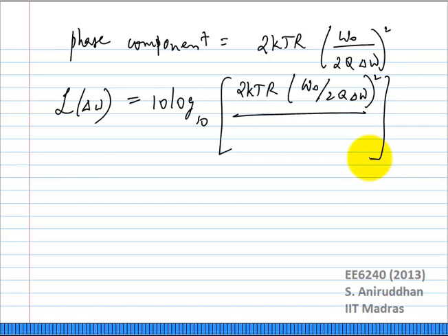The power of the signal. So I am using a voltage squared quantity for the noise. All I have to do is find the output amplitude, take the square of that, and that will give me my signal power in voltage squared terms. I'll just call that Vs squared. Depending on the particular amplitude you have, this will change, but this is your number.